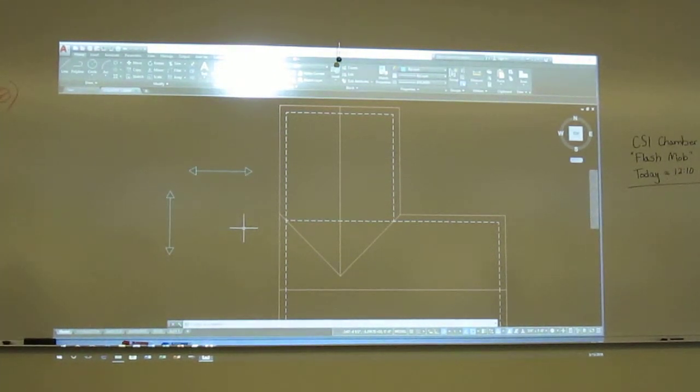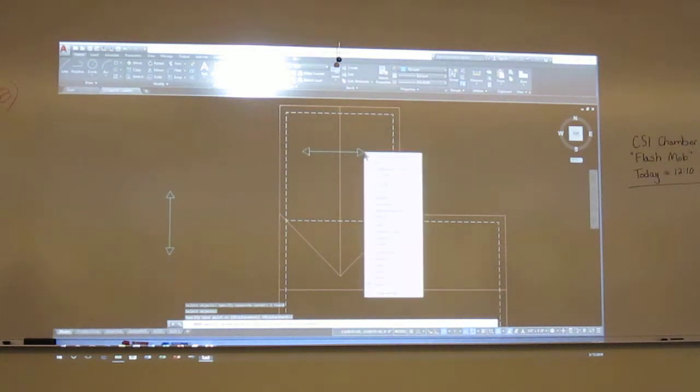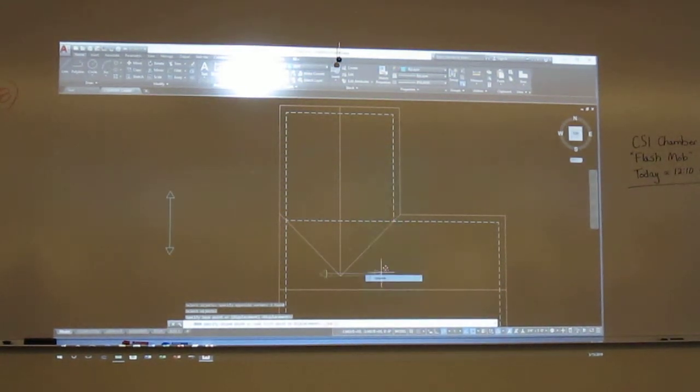Now, when I put it in, those arrows terminate on the outside of your bearing edge. So if you just watch me for a second, and then I'll let you do it. I'm just going to take this character and move it. I use probably the nearest snap on this because you may have some other things you want to be able to move. You're not really sure where you're going to place it, but I'm going to snap it to the outside of that wall.